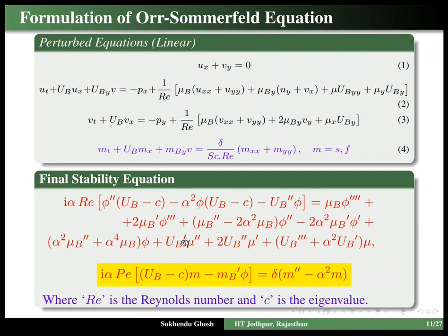Okay, so now from this governing equation, the next part is you have to find your perturbation equations. To find the perturbation equation, you have to choose variables which are a combination of base flow and perturbations, and then simplify. If you remove the non-linear terms with respect to perturbation, then we end up with a linear system in perturbations. However, these are again a coupled set of equations.